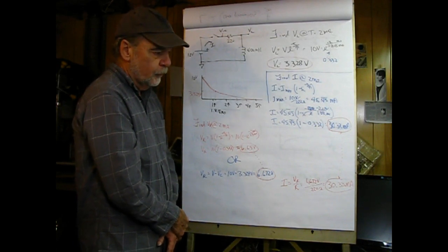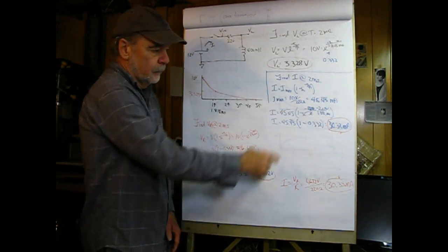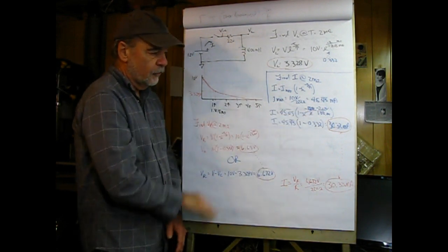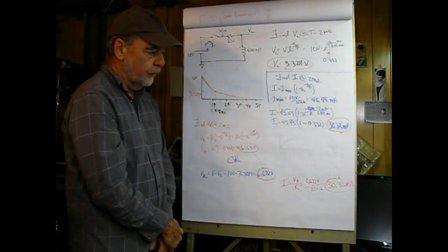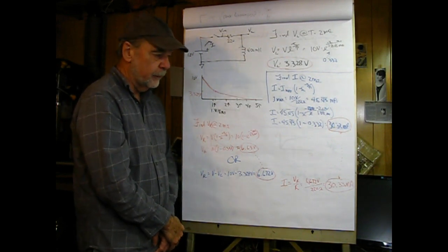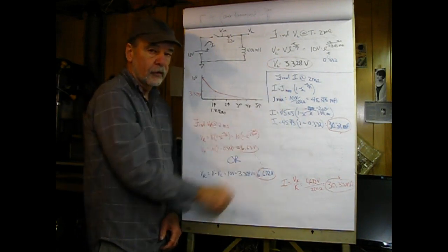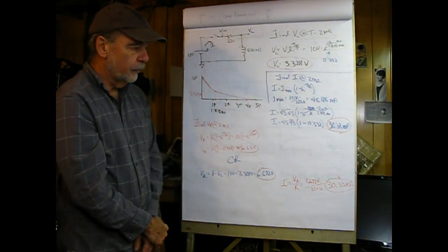So what we'd use to find the current is this Imax value, with the same asymptotic approach, and what we end up with is a current of 30.32 milliamperes. I shouldn't say maximum current. This would be the current at 2 milliseconds. So that's not too hard to find.